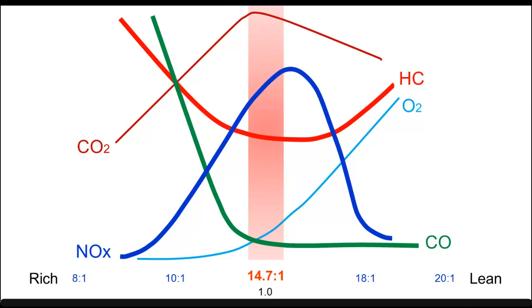To summarize tailpipe emission testing, hydrocarbon, carbon monoxide, and oxides of nitrogen emissions may remain low through minor mixture excursions or other faults. Carbon dioxide levels of less than 13% indicate mixture is rich or lean of stoichiometric. Catalytic converters produce carbon dioxide, raising levels above pre-cat values.